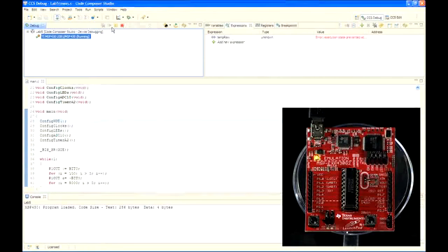If everything's working correctly, the red LED, that's what's in the while loop, should be blinking about twice per second. This is the while loop that the timer's interrupting. The green LED should be blinking about once per second. This is the rate that we're sampling the temperature sensor. And looking at the board, that looks pretty good. Go ahead and click Suspend to stop the code.